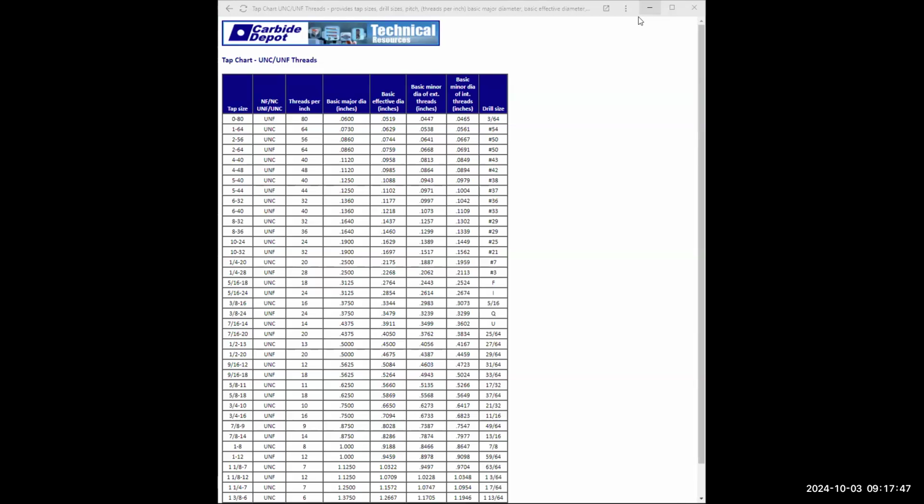and click on this. And we're going to make this C bore, which stands for counter bore. Percent C space 1.00 DP, delete through. We're going to make this 0.5. Oh, not 0, this is 0.50. Click on the screen, anywhere, enter. I hope you got that one. That was a little tricky.